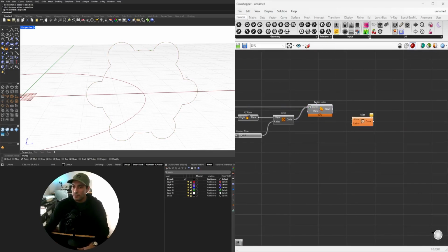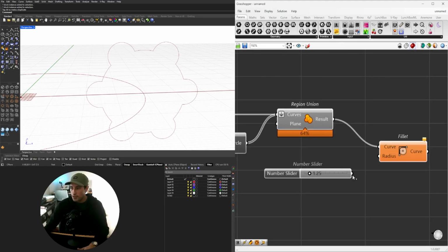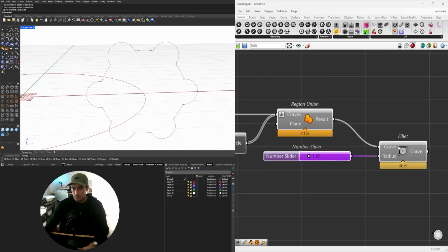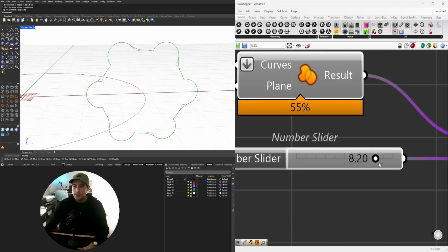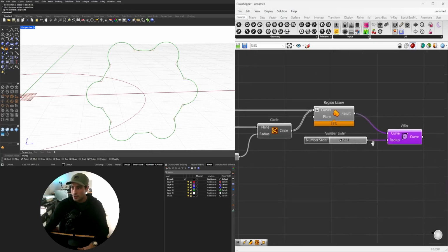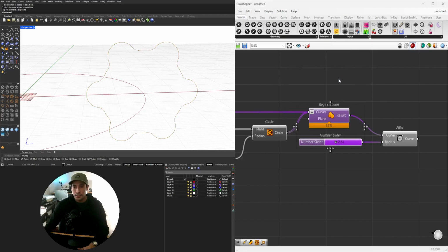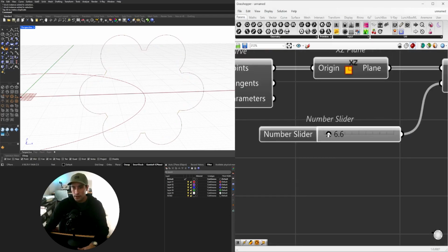Now with this one, I like to use a fillet so we can round off these bits. So I'll use a small slider, so 1.25, which will go from 0 to 10 and give us 2 decimal points here. Now you'll see that there's a limit to how far you can go, but even then this would actually create a cool shape where it goes to an indent here and it's smooth. So those are the cool things that we can discover as we create a script, is the opportunities that we sometimes don't think of when designing.